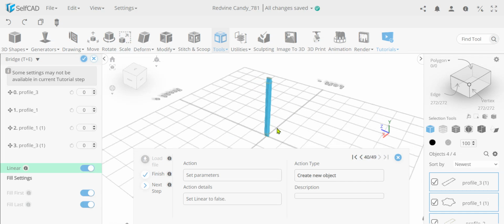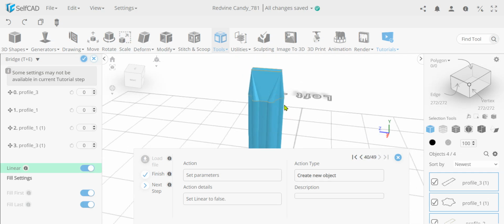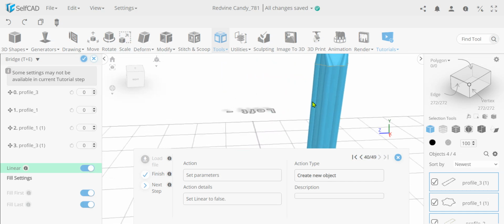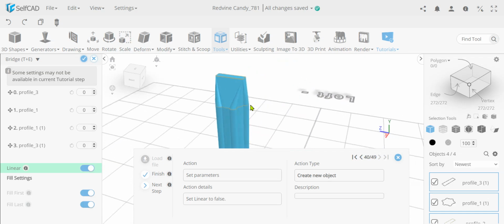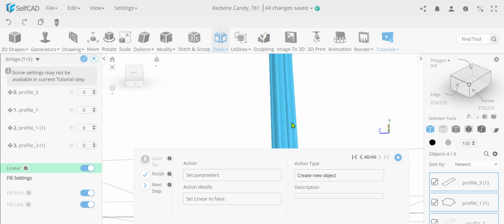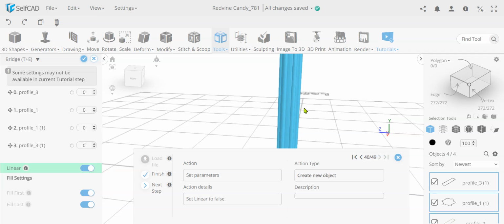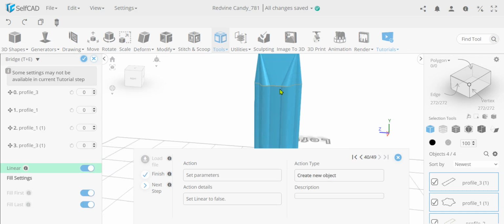Okay, the other thing I want to show you here is if I zoom into it, you see this is exactly following the details from the mesh. So it copies exactly identical, for everything, and it goes down the entire thing, and it is not like what you typically know as a loft. Think about a loft as kind of like splines. When you draw something with a spline, you expect it to be altered, to be rounded, to be smoothed out basically. In this case, this is not, and this is because we have the linear on. This means it needs to keep exactly the shape.